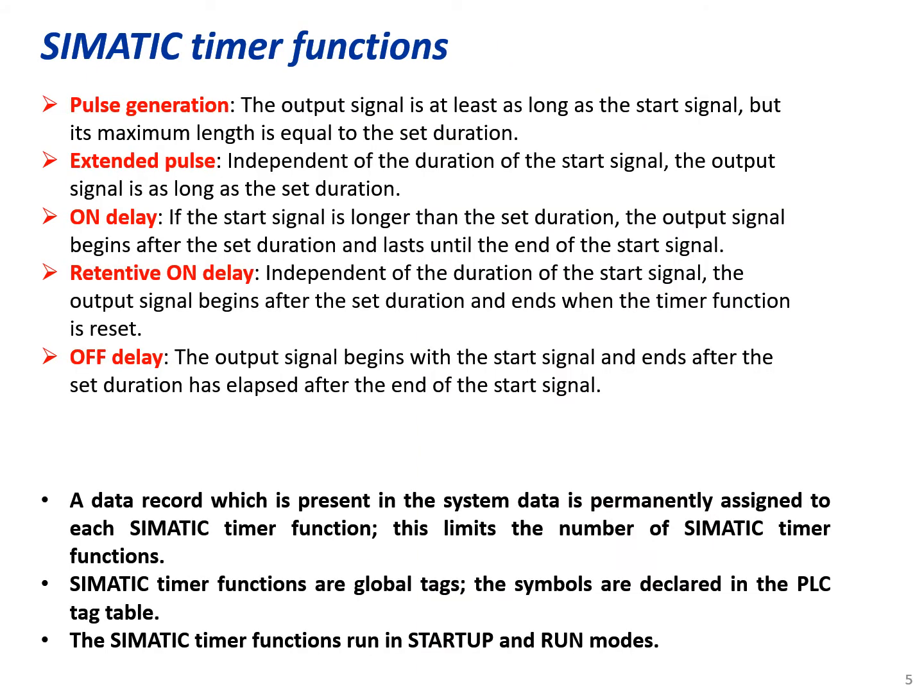What types of timers do we have? We have pulse generation, extended pulse, on delay, retentive on delay, and off delay timers. Pulse generation: the output signal is at least as long as the start signal, but its maximum length is equal to the set duration.